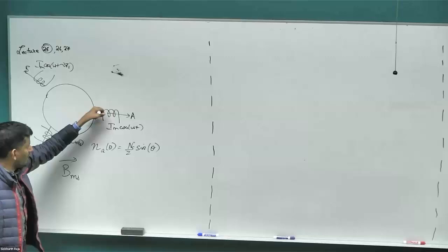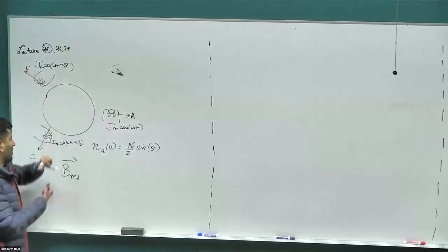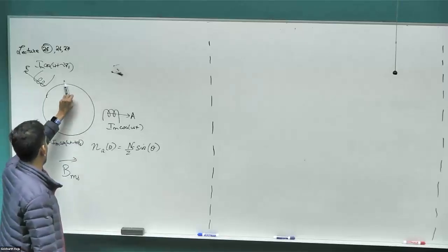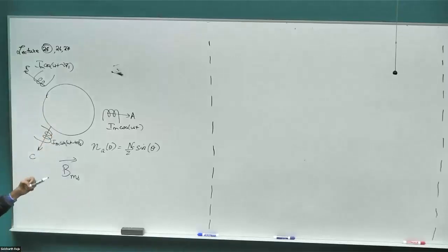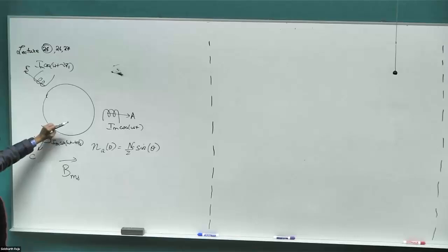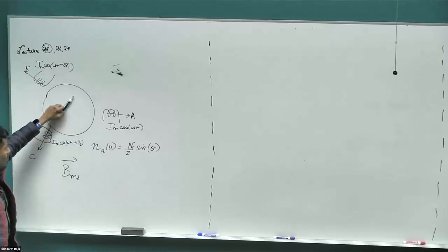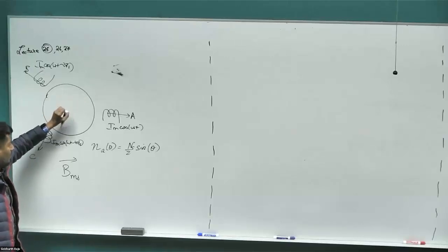As time goes on, as the A phase current starts to reduce and the B phase current starts to pick up the slack, the B field is going to start to rotate, right? So you can think of the maximum of the B field rotating around, and then everywhere else it will be spatially distributed in a sinusoidal manner. So going forward, you can forget about all the other distribution that we have. You can just visualize the peak of the B field alone as a space vector that's rotating in time, right? So it has nothing to do with the rotor.